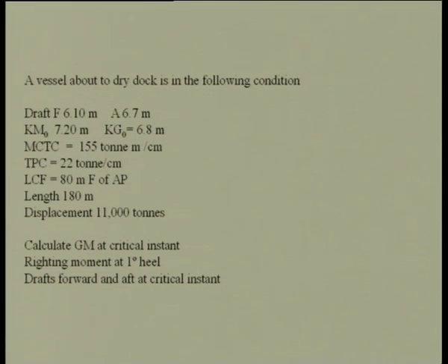Then KM0 is 7.2, KG0 is 6. These are the hydrostatic data. Then MCTC is given, TPC is given. Longitudinal center of flotation is 80 meter forward of aft perpendicular, length is 180 meter and displacement is 11,000 tons.